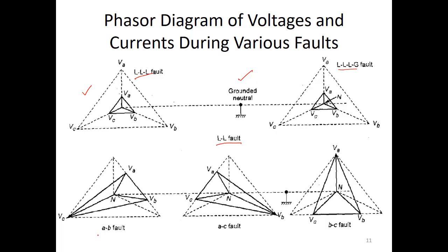This is the line to line fault, that is the phase to phase fault between A and B, that is the fault when phase A and phase B are short circuited without involving the ground. Similarly, the voltage also decreases, we can see here, and the fault voltage will obviously lag. Like if you see the circuit here, let us say this is your network and